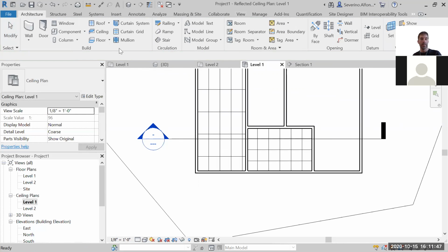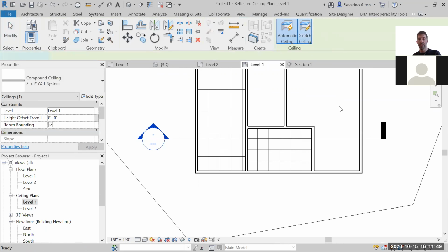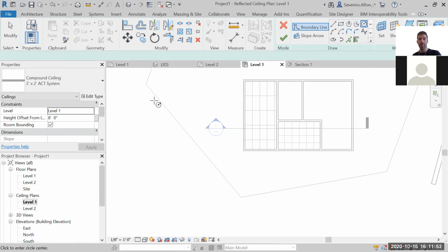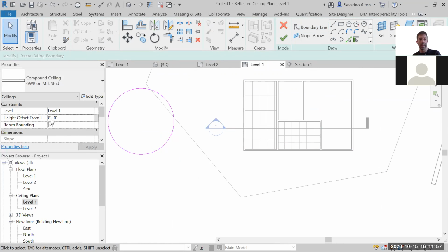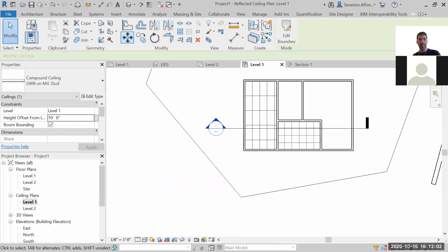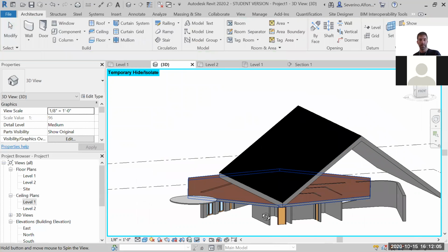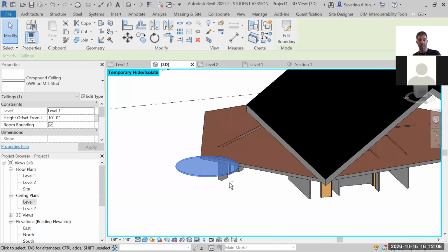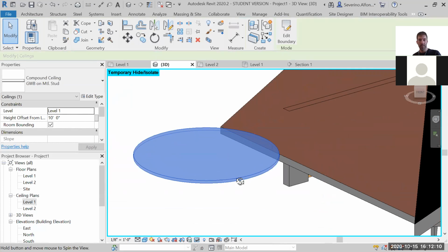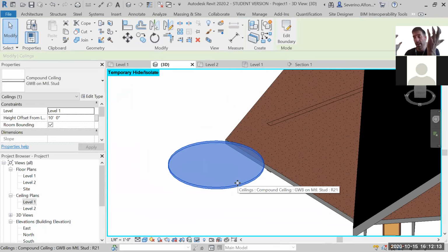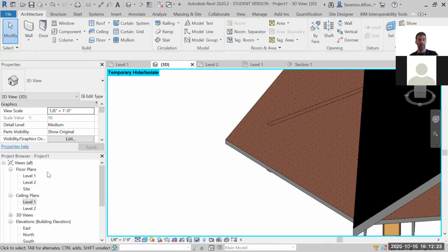If you actually create a ceiling and you have the second option, sketch, that means that you can do any type of ceiling of any shape and at any height. There is my ceiling. Many of you tend to do, and I like as well, this separated ceiling in the center, so it's not exactly going to the edges. You might want to recess some lights behind the ceiling, so you could actually do that with no problem.